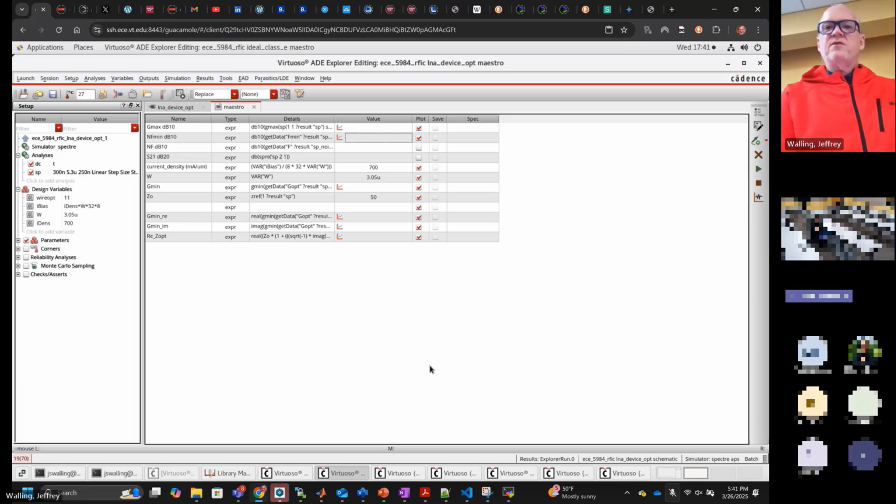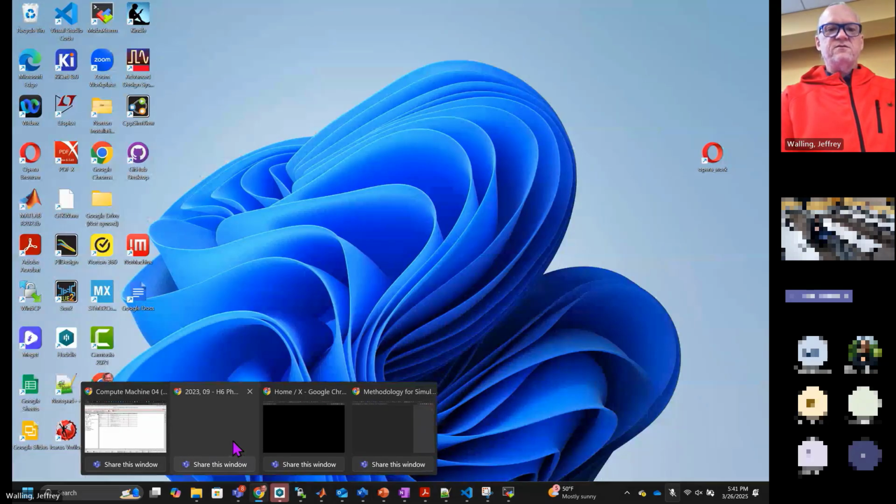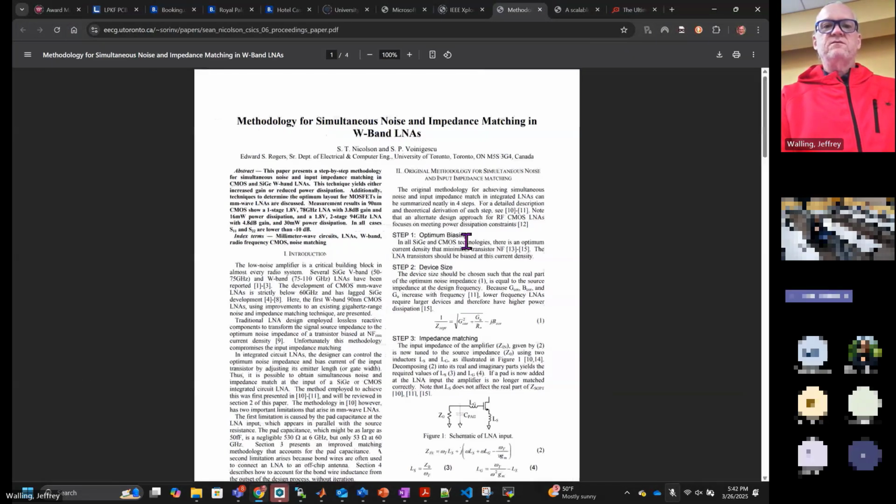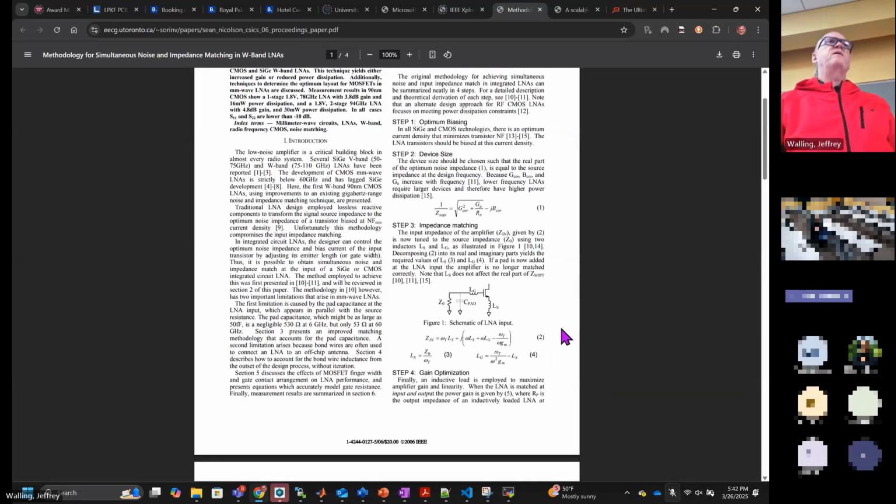The paper that I uploaded from Sean Nicholson and Professor Sorin Voinigescu just before class goes over a more optimal strategy for minimizing noise figure. In this, you'll notice he says step 1 is to optimize the biasing, so figure out what the current density is and use that.